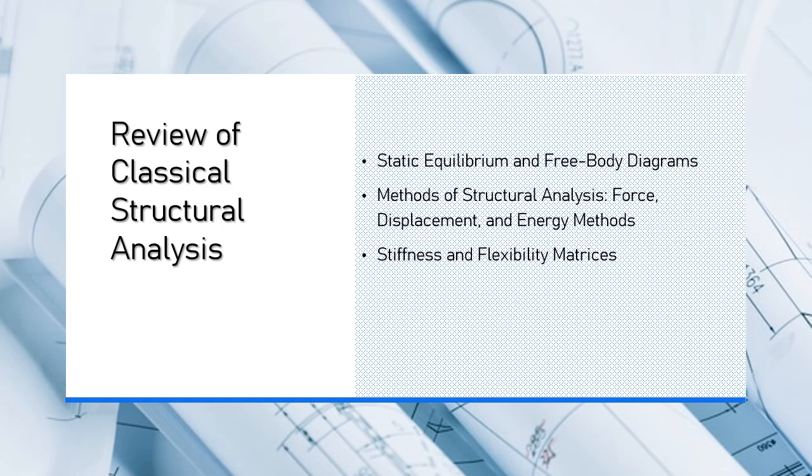After solving for the internal forces, the next step is to apply compatibility conditions, which ensure that the deformations, displacements, of the structure are consistent with the assumed displacements. These conditions are used to find the values of the redundant forces by ensuring that the deformation of the structure is physically possible. Reintroducing the redundant forces: finally, the redundant forces are reintroduced into the system to obtain the complete solution.